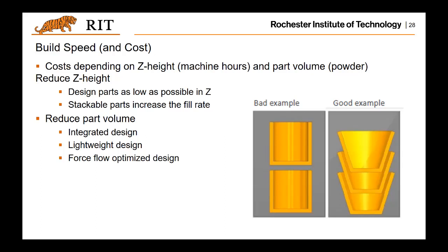Again, the build time of this SLS depends on how fast the laser scans on the build platform, and also how long it takes to spread the material, and also lower the build platform.